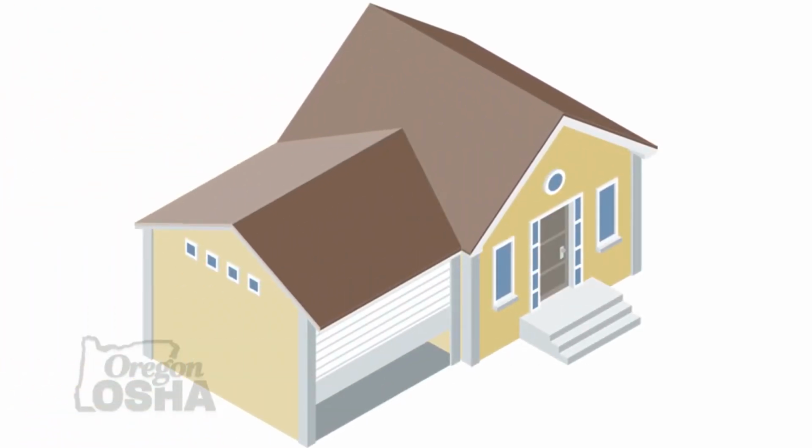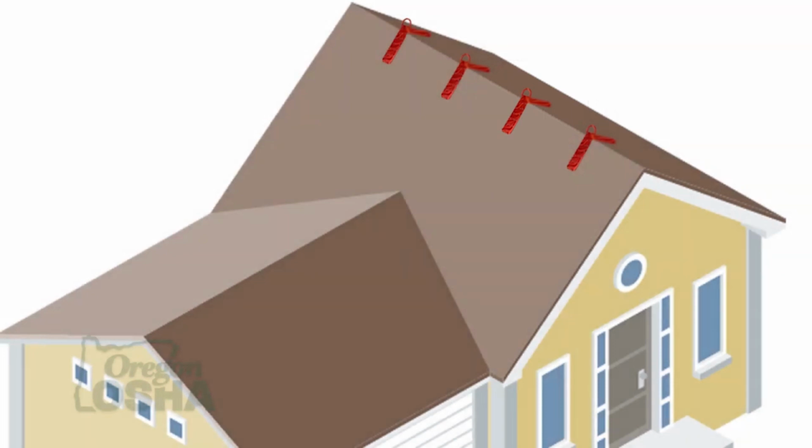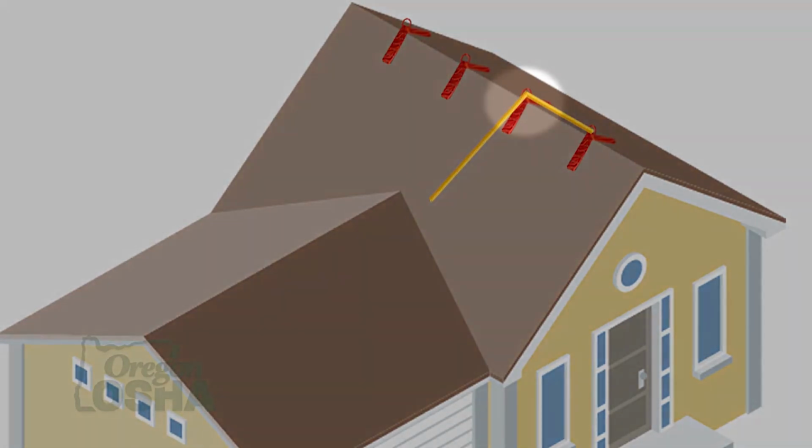When you're up on a roof, if you're not going to put a rat line up or a horizontal lifeline up, right? Take 4 or 5 anchors and put them up there, all the way across the roof. Hook off to this first anchor. Okay, that's your anchor point, right? But I need to work over on this side, and it's out of my swing fall, because we give you 30 degrees. From 0, we give you 8 to 10 feet. So put another anchor 20 feet. You've got 10 from this one, 10 from that one, right? Then walk over to that anchor, pull a carabiner out of your pocket, put it in the anchor, and put your rope through it. Where's your new anchor? Right here. You can do that as far as you've got rope, and then you just come back, but you're always tied off. And it gives them freedom, especially guys doing tear off.